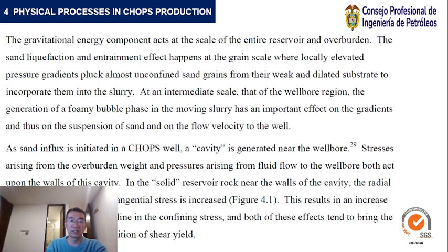As the sand influx is initiated in a CHOPS well, a cavity is generated near the wellbore. Stresses arising from the overburden weight and pressures arising from fluid flow to the wellbore both act upon the walls of this cavity.